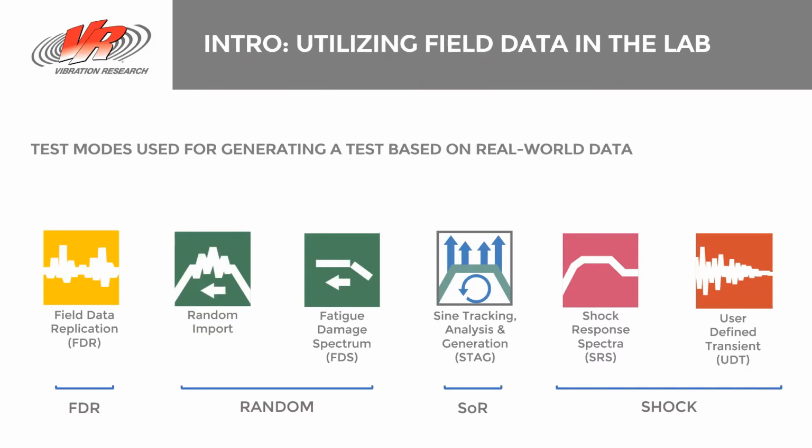So it takes that time history file and plays it back exactly one-to-one, just like if you were playing a song on a speaker. It's playing it back exactly how it found it, right? This can be great because we're always running exactly the same test, the exact same frequencies, the exact same accelerations at the exact same time, right? So it's a very repeatable test, extremely repeatable.